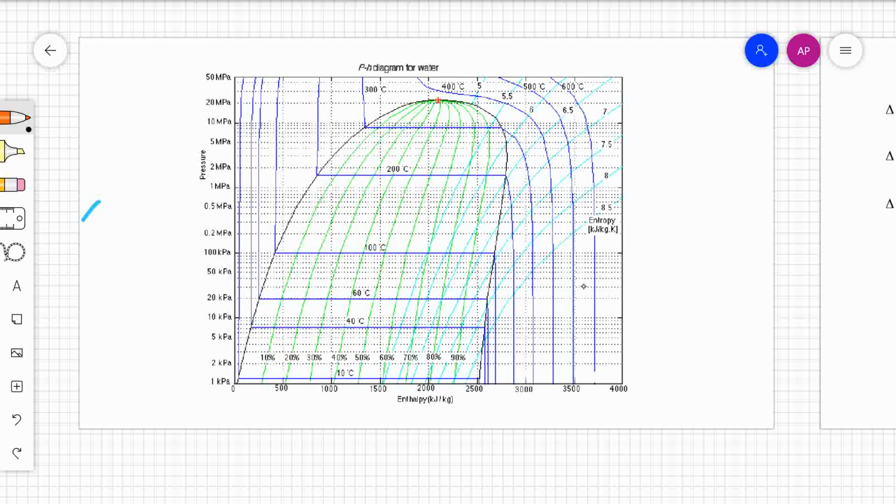So it is very clear that if you boil at reduced pressures, the enthalpy for vaporization is high. But if you boil at increased pressures, the enthalpy required for vaporization reduces. And it's an obvious fact that at the critical point and over and above it, there is no enthalpy of vaporization. Therefore, above the critical point, you cannot have a concept of boiling because there is no phase change which occurs.